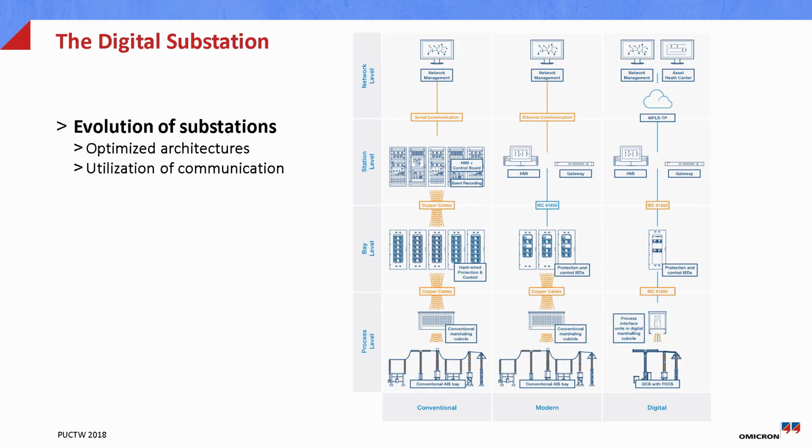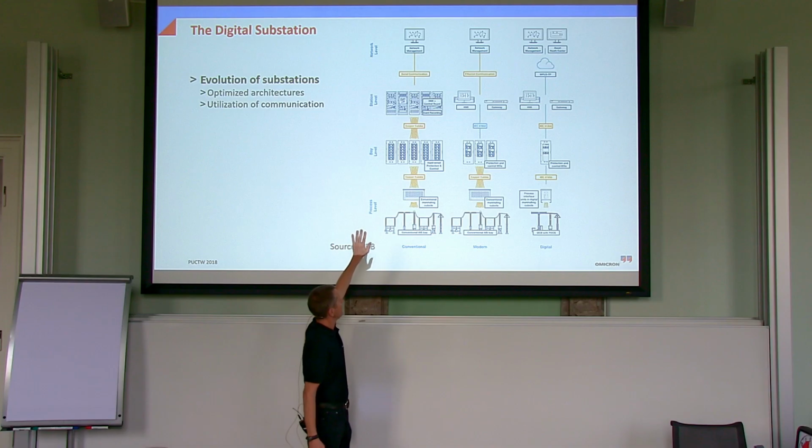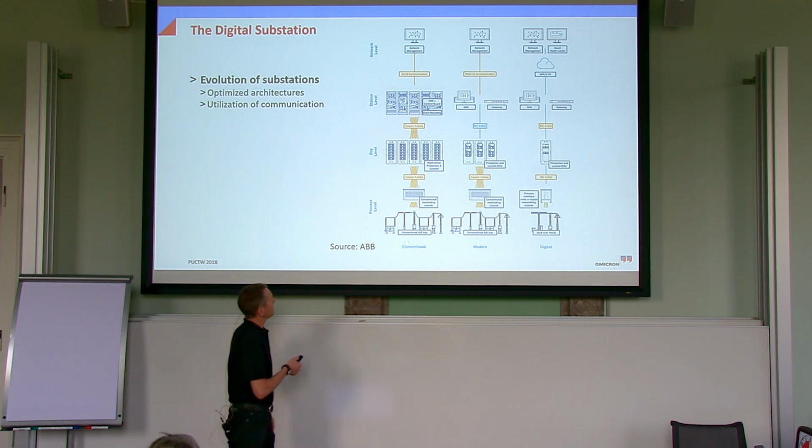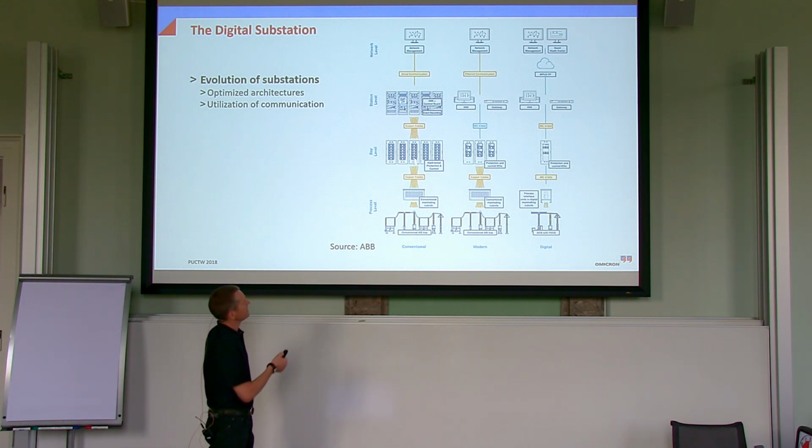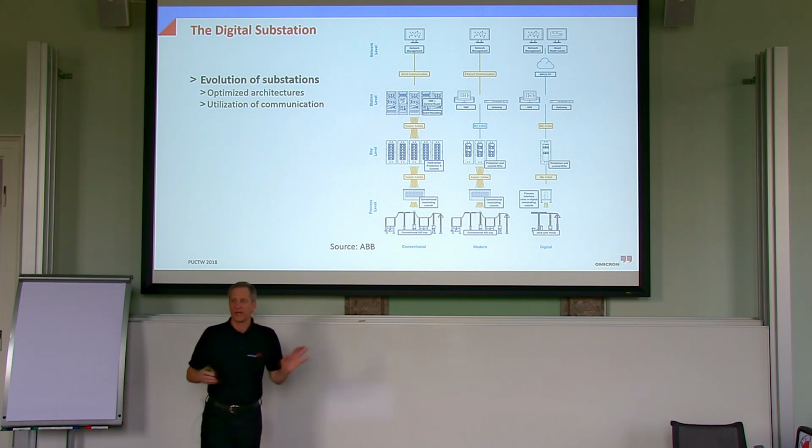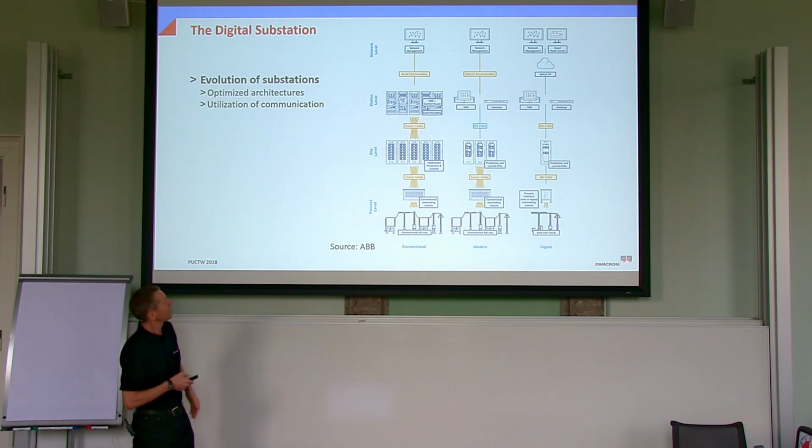Okay, the digital substation, how do we define that? Here I have a picture, and it's not my own creation. I got it from a brochure from ABB. They have very coarsely lined up how this evolution of substation technologies evolved over time. They have here this conventional architecture where everything is, let's say, parallel wired up to the station level, and then we have some kind of, maybe sometimes proprietary communication to the network level.